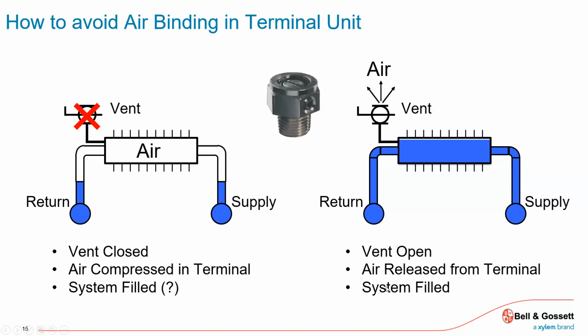Something simple: if I'm filling the system and I don't release that air on initial fill and the air stays, it's going to get squeezed by the incoming water, but it's not going to disappear, and it's going to reflect down in the basement on the gauge as pressure. And you're going to say, okay, I got the water to the high point, it's under the right pressure.